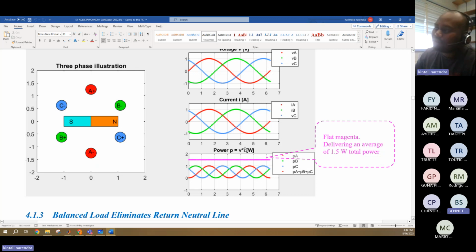Even though you do four phase, six phase and all, still the power limitations will be almost the same. There won't be much gain, so three phase is more viable, basically. That's why we go for three phase with 120 degrees phase difference, because of the constant power it provides. Now we know that there is a phase difference with the AC power supply.